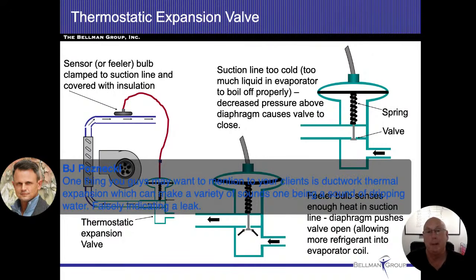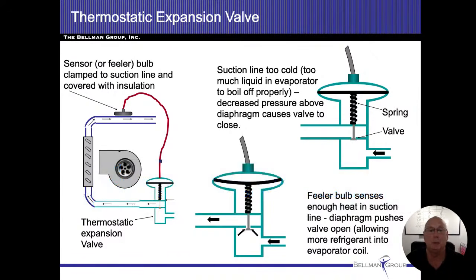In this case, yes, you hear that dripping. What's happening is the ductwork gets warmer, it's going to expand. As the ductwork gets colder, it's going to shrink. I'm sorry, BJ, I didn't understand what you were mentioning to me when you said thermal expansion before. As it shrinks and expands, there are pieces that slide in between each other, and it's just a little bit of movement as it comes through. So sometimes it sounds like dripping water.